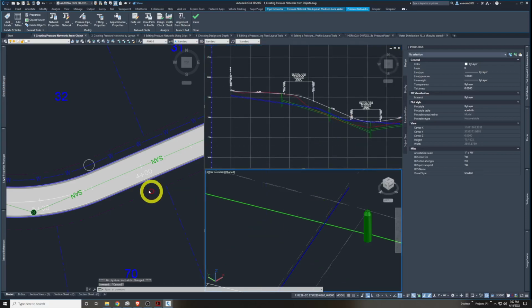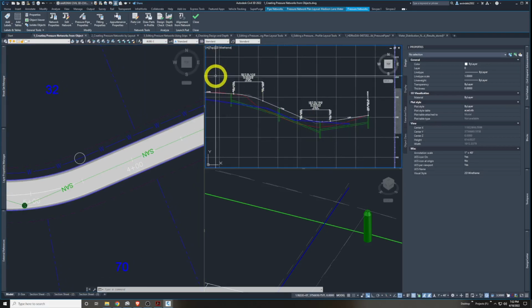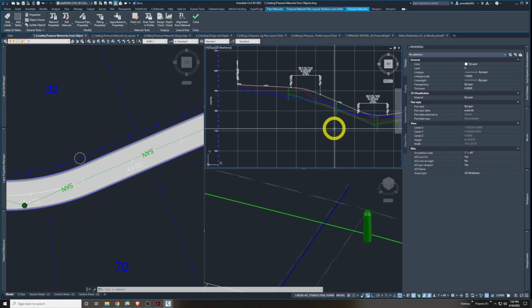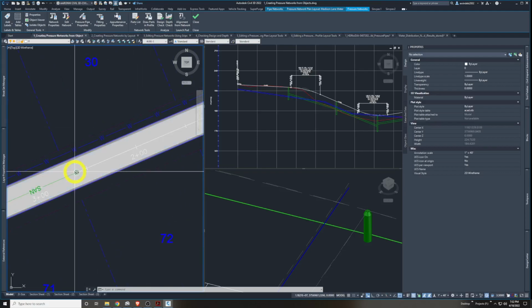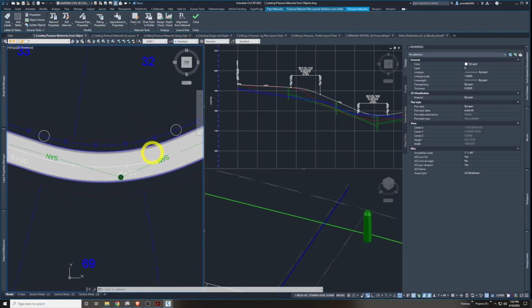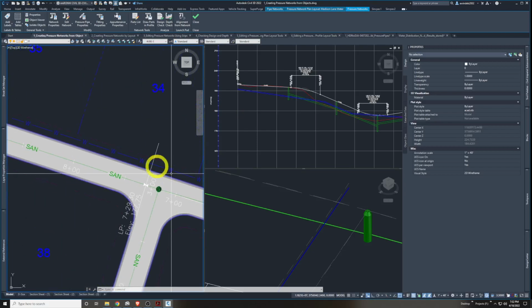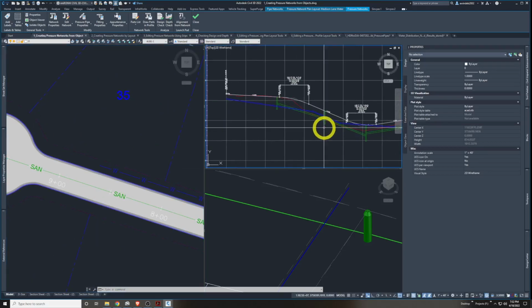which has some conflicts with, you can see the sanitary sewer gravity pipe is also kind of running in a way parallel to it somewhat. In some spots it very much is. So in plan view here, you can see the sanitary sewer with its sewer manholes is for a time running parallel with our water pressure pipe, okay, as we go. And we can see it similar here in the profile view, which is helpful to just get your head wrapped around that to start.